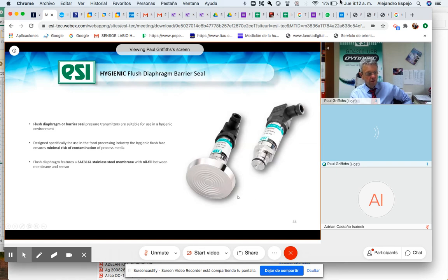The big concern in the cleaning process is to be very gentle. You can't use high jet pressure, or a brush or a screwdriver to clean the surface. You have to use warm water with certain chemicals that will ensure that the surface is clean but not damaged.